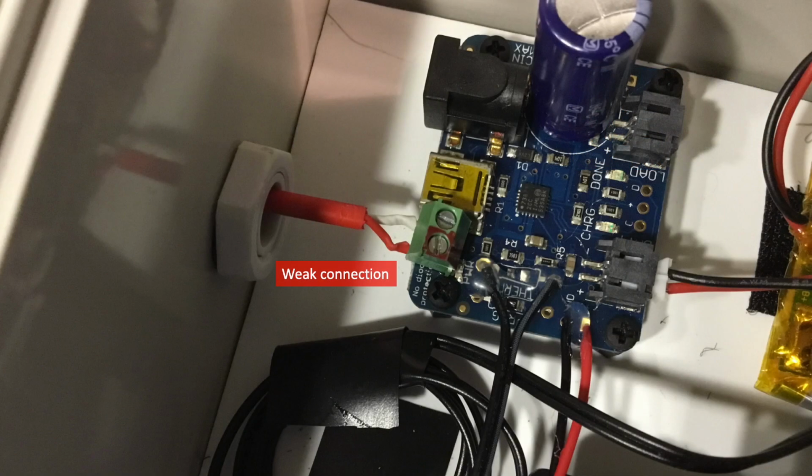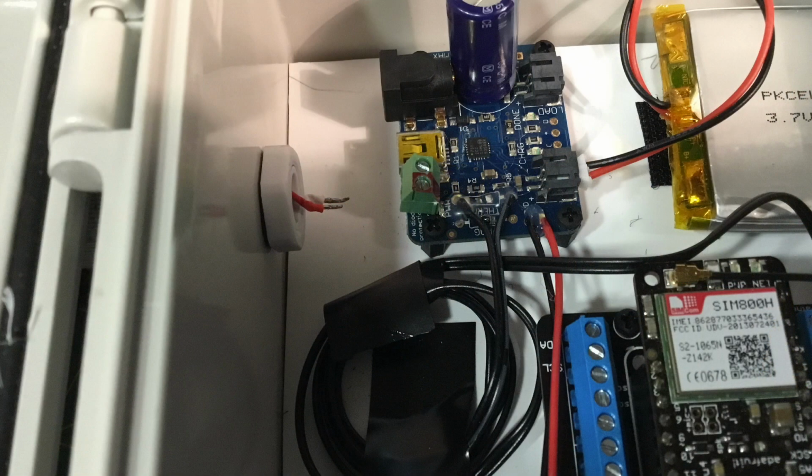Before replacing the circuit in my REM box, I'll take this opportunity to make a few improvements. First, I've discovered this terminal block on the solar LiPo charger is a point of weakness. I've observed the solar cable wires can detach if the watertight fitting that feeds the wire through the box becomes loose, or if the box is jostled for any reason. This will eventually lead to a dead battery. For some of our remote locations, that means we'll have to drive out to service the unit, which defeats the efficiencies we're trying to realize.